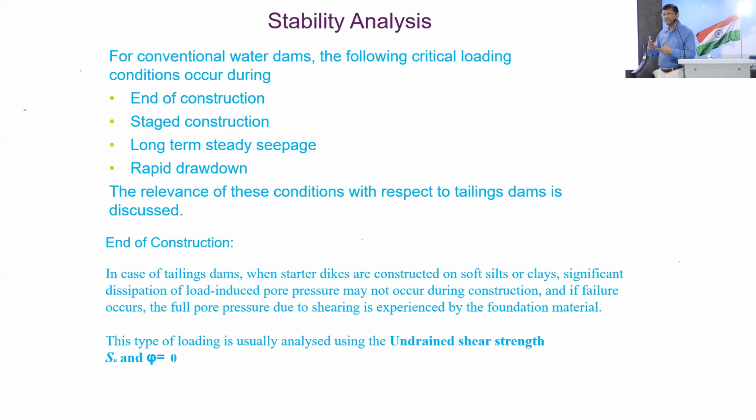Otherwise, in the case of tailings, we don't see that effect of rapid drawdown, because most of these facilities are full of tailings, and we have a very small portion of storm water present there, because most of the water is always recycled. When the tailings are settling, the suspended solids settle and the water is pumped out again. That's the technology mostly everybody follows.